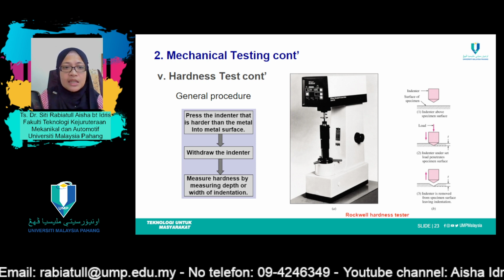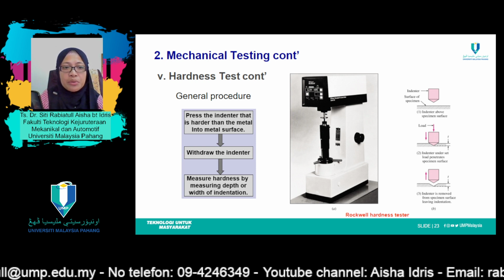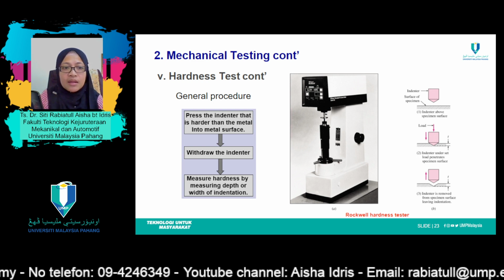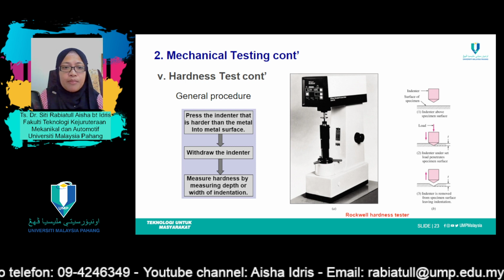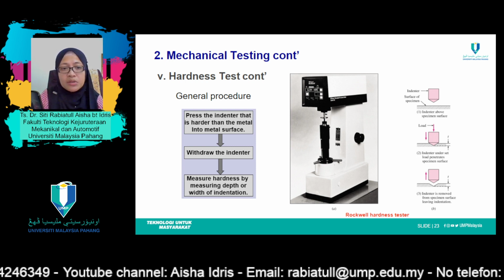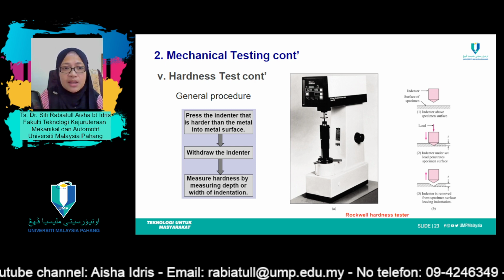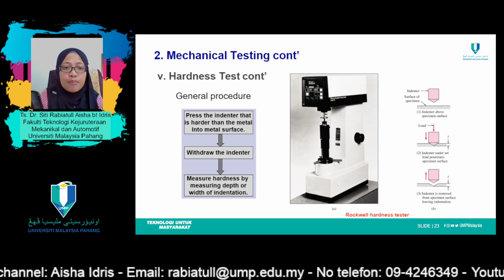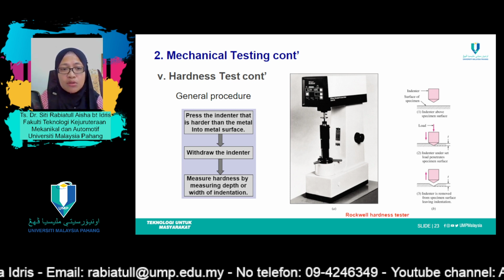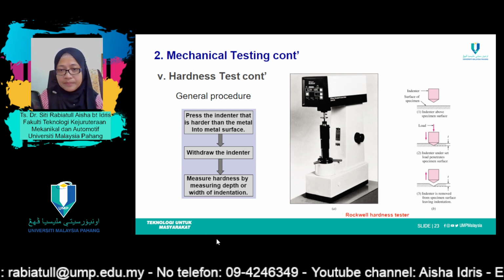The hardness is determined by measuring the depth of indenter penetration or by measuring the size of the impression left by the indenter. Hardness tests that measure the depth of indenter penetration include Rockwell, instrumented indentation testing, and ball indentation hardness, whereas hardness tests that measure the size of the impression left by the indenter include Vickers, Knoop, and Brinell testing.